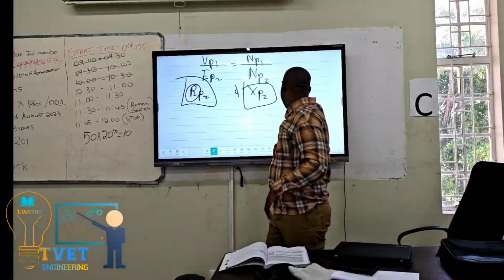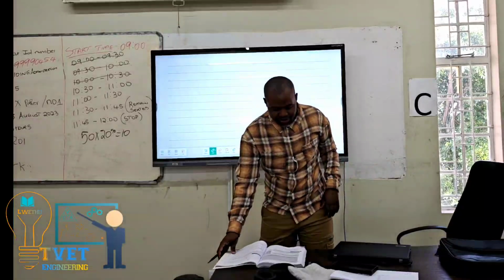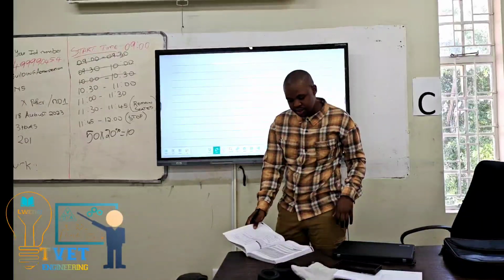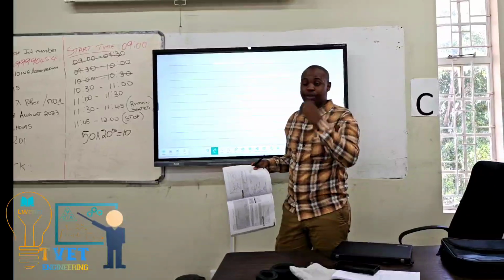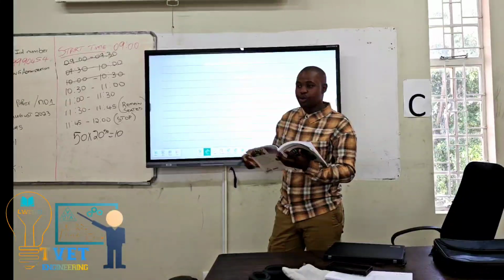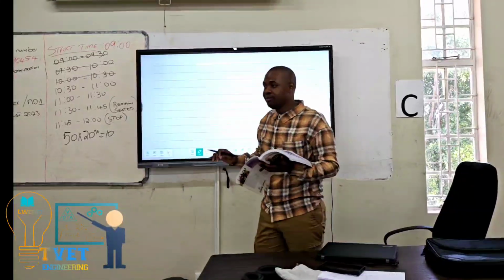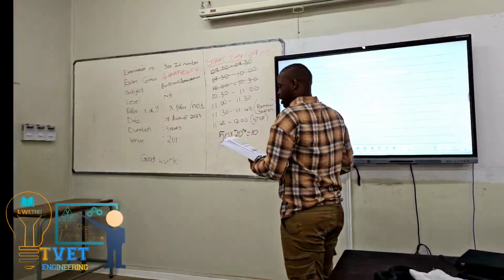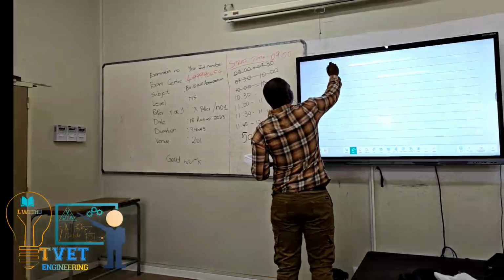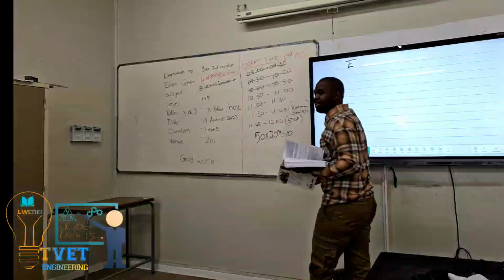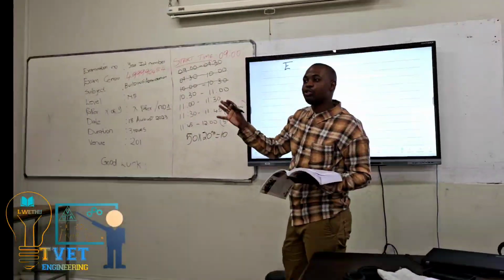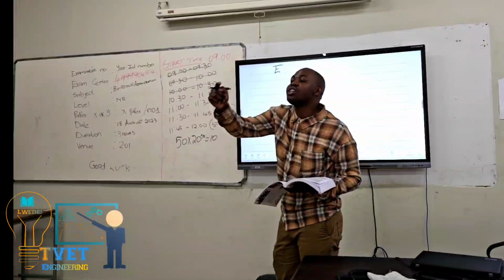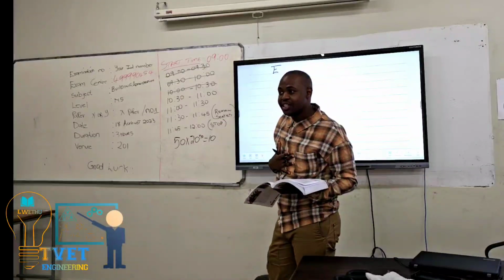Let us go to the next page and see which are these frequency-dependent values. Notice that rotating values are marked to show they are rotating values. For example, the induced EMF in the rotor is frequency dependent.